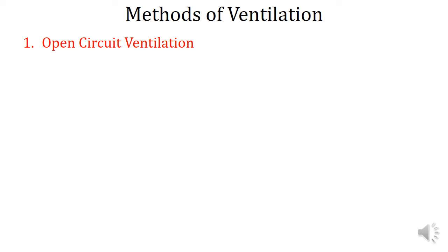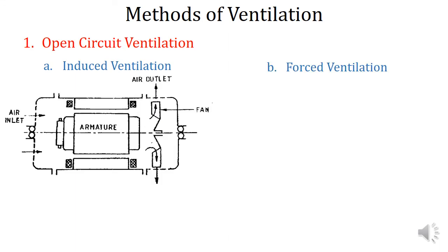Open circuit ventilation means the heat is given up directly to the cooling air and the air is being continuously replaced. That is known as open circuit ventilation. It is again classified into two: induced ventilation and forced ventilation. Induced ventilation is as shown in the figure.